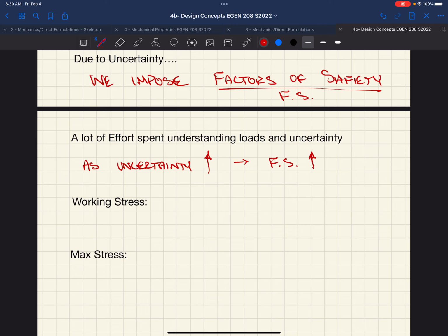Whereas if we were going to look at, say, one of the beams above our heads here, right, a very repetitive sort of system, lots of them there, there's the potential to have redundancy, right? One sags a little bit or fails a little bit. Some of the other ones might be able to pick up the load. That's where we're down in the like 1.7 range, 1.67, okay?